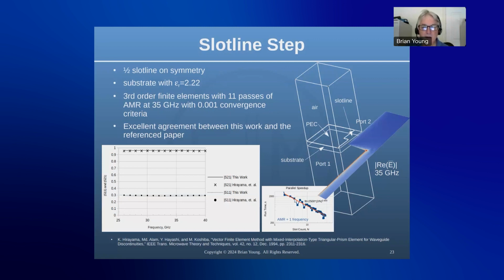There's a little plot to the right, repetitively solving with adaptive mesh refinement at one frequency, plotting time versus the number of unknowns on my dual processor Xeon, and then fitting it on a log-log plot. The exponent is 0.655. So the efficiency for this problem is 0.655. As far as I can tell from the literature, for a memory-intensive application, that is a typical number. If anyone is aware that this 0.655 is a very poor number, I would love to hear from you.